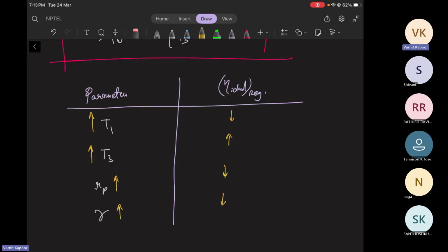But when you reach the maximum pressure ratio, the net work was 0 and eventually your efficiency will be 0. So you can increase the pressure ratio only to a certain limit. Otherwise, the temperature at the compressor outlet will be higher than the metallurgical temperature of the turbine.